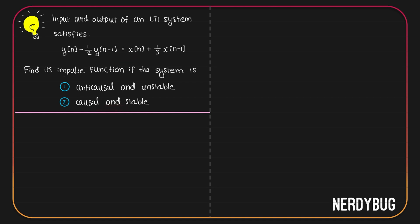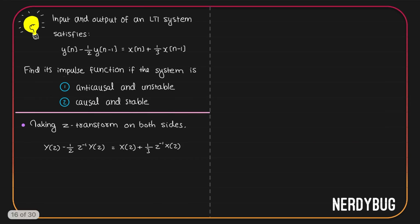So the first thing we are going to do is to take the Z transform on both sides. On the left hand side, we have y of n. Its Z transform is y of z. We have minus 1 by 2 y of n minus 1. Its Z transform is going to be minus 1 by 2 z inverse y of z. This is equal to the Z transform of x of n, which is x of z. The Z transform of 1 by 3 x of n minus 1 is 1 by 3 z raised to minus 1 x of z.